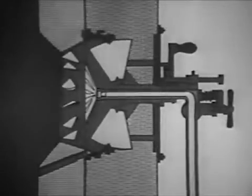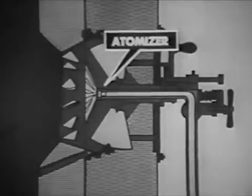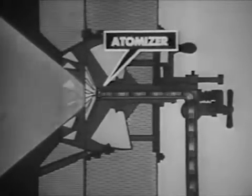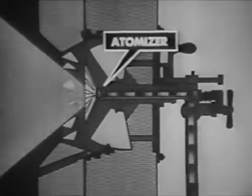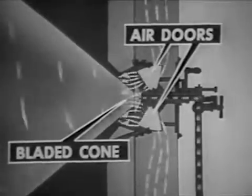Oil that is burned in the boiler furnace. As seen in this view of a typical burner mounted in a furnace wall, the burner's atomizer reduces the fuel oil to finely divided mist-like particles. That is, it atomizes the fuel oil. Then the air doors and the bladed cone in the burner register mix these particles with air to form the combustible mixture. Although all burners perform these two functions, atomizing the oil and mixing it with air, different types of burners atomize the oil in different ways.